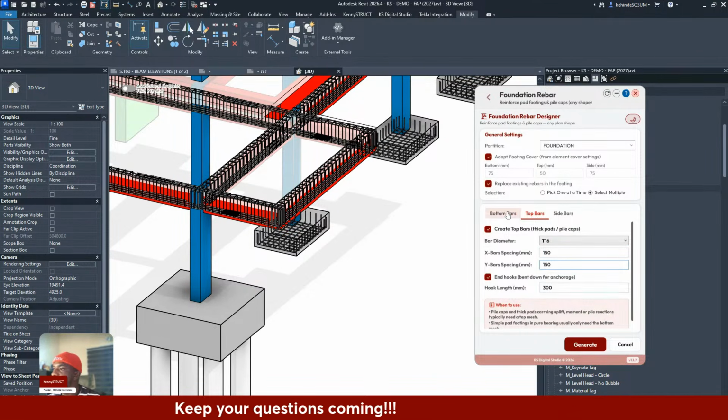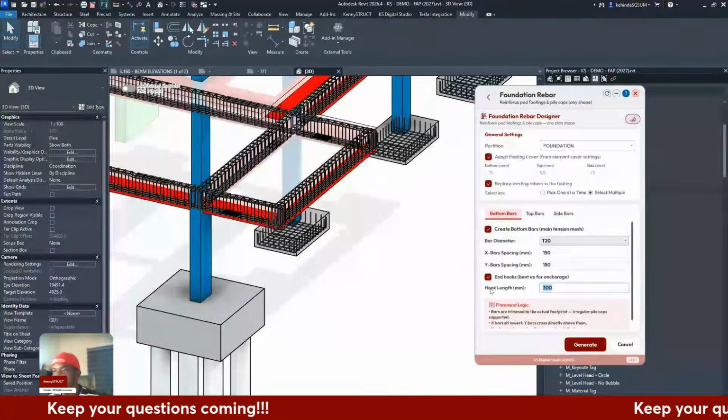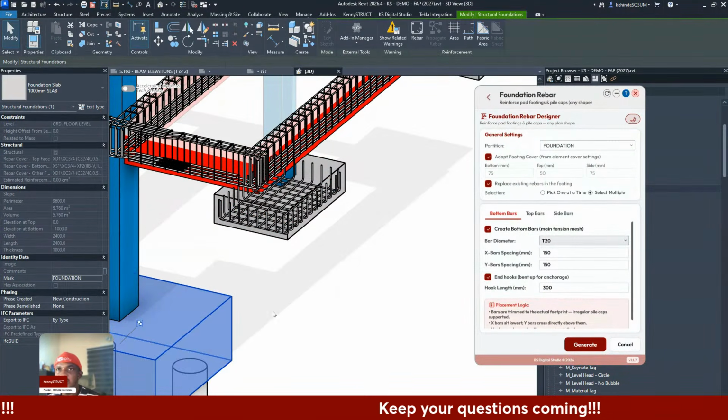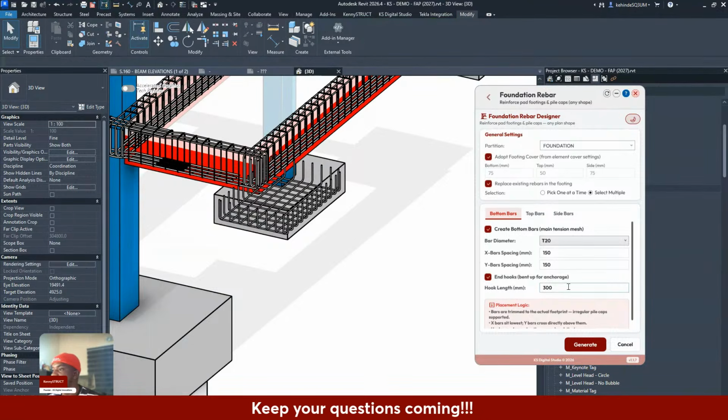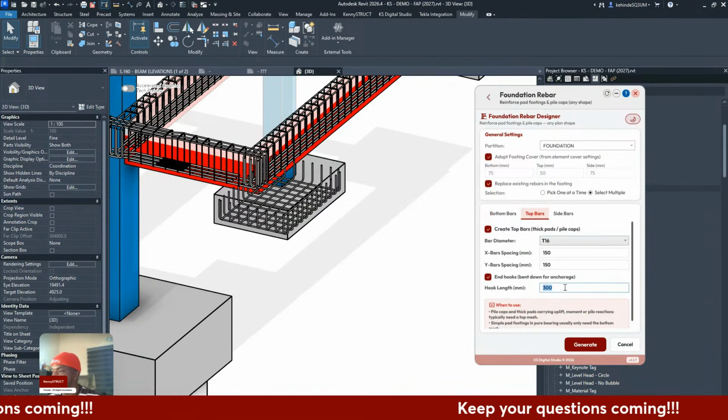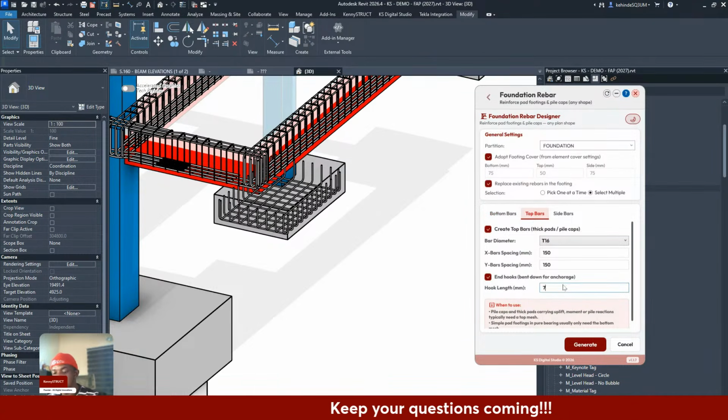And the anchorage, that's the hook. Yeah, let's say 700. I think this pile cap is 1,000 and 1 meter of 6 pile cap. I'll just make it 700. And top bars as well, 700. That's the hook that goes up.